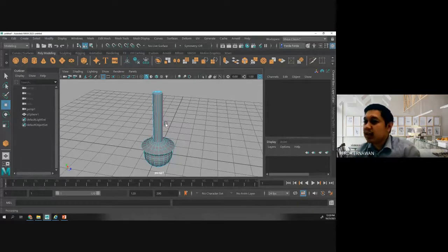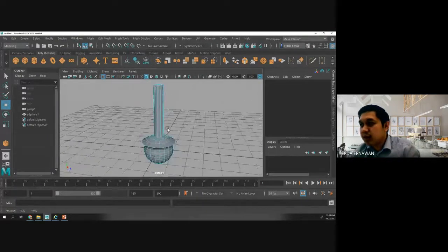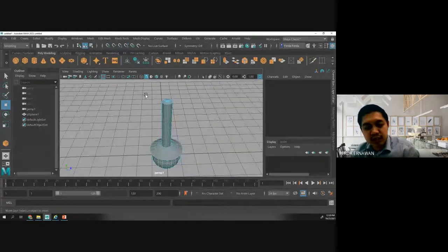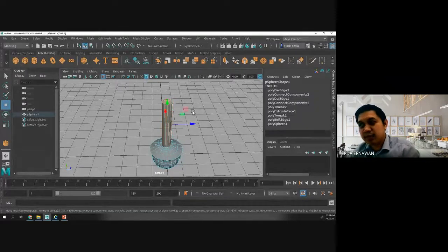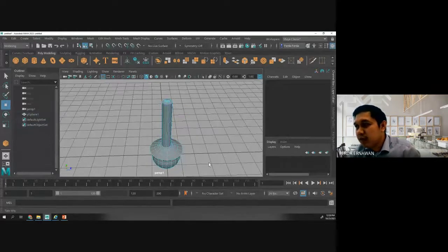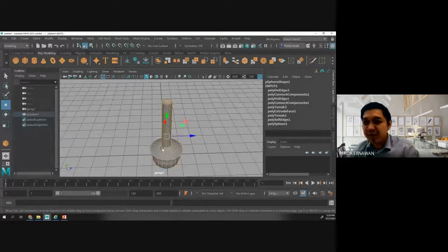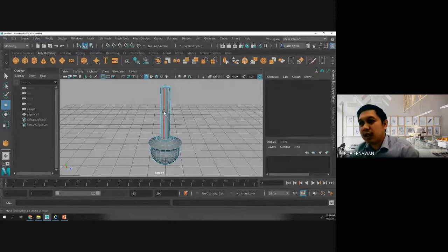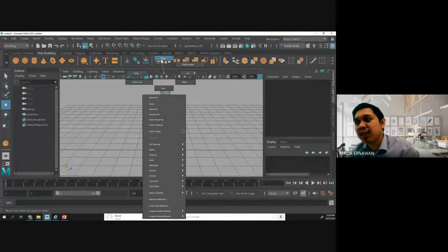So for the subdivision, what should you do here? Be careful when you select the object. If you select like this, this is the key. If you select like this, it is wrong because you are covering the top one. If you select like this, also wrong. You are covering all this. Actually, in your design, I want to make some subdivision in this area, only this cylinder for example. So you have to choose number one. Don't forget, choose the edges. Don't choose the vertex or face.